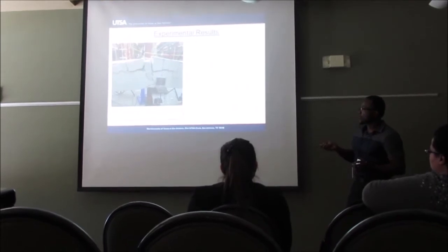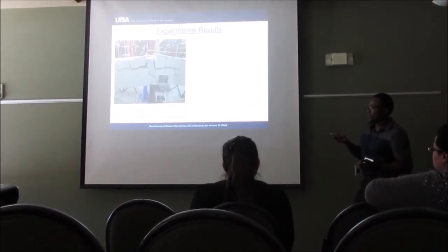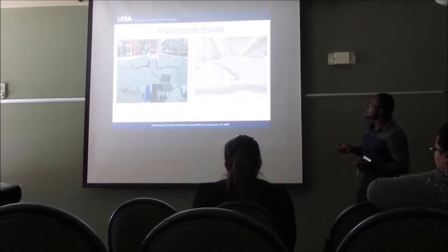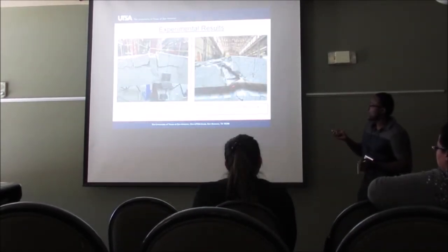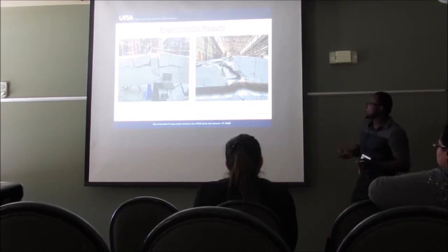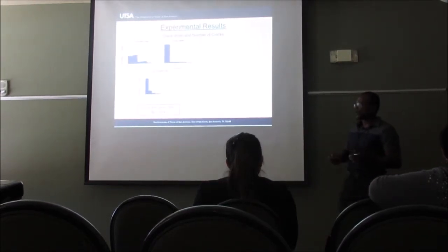And looking at these cracks towards the end of the test, when you look here, you're able to fit a piece of paper easily in these cracks. And for the deformed bar, the failure was a big catastrophic failure that we observed. And that's due to the unstable drift ratio that we saw.